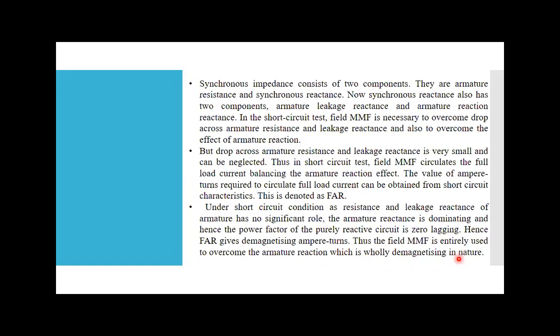If you are aware of the question paper, in GTU they ask about this. What is the effect of armature reaction when I have a purely capacitive load? In a purely capacitive load, the effect is magnetizing. And in a purely inductive load, the answer is demagnetizing effect. In the paper, we have both questions: what is the effect of armature reaction with only a capacitive load, and with only an inductive load. In an inductive load, we have a demagnetizing effect.